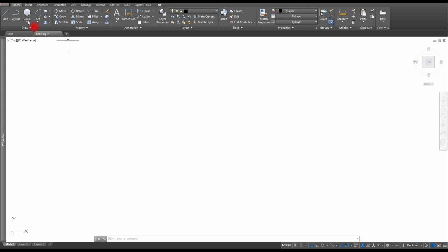Alright, so the first thing I'm going to do is just create a long line going down. Make sure I turn my ortho on, and I want to go down a distance of 20. And I know some of you might be looking at that I have this on decimal. I can switch to architectural, but this will take fractions, and none of our numbers, as I can see on the drawing, are so large that I would have to use architectural units. So I'll create a line that's at 20.